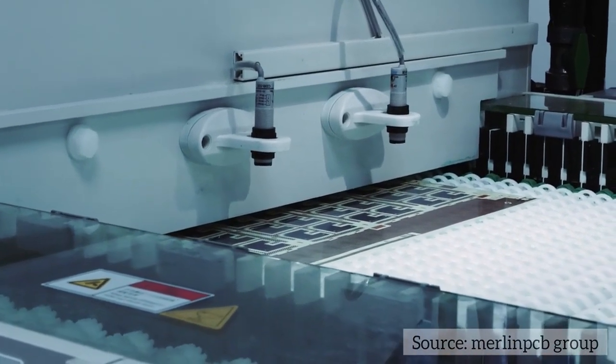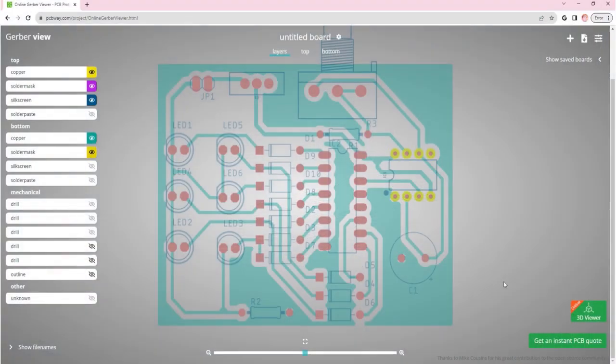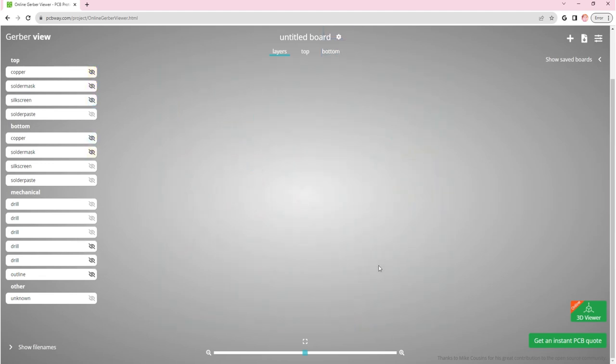Printed circuit boards are designed in a specialized EDA, Electronic Design Automation, or a CAD, computer-aided design system that further generates board manufacturing data based on which circuit board fabrications are commenced. PCB manufacturers won't fully understand all details of a PCB design file unless a Gerber format file is contained in it as reference and guidelines.